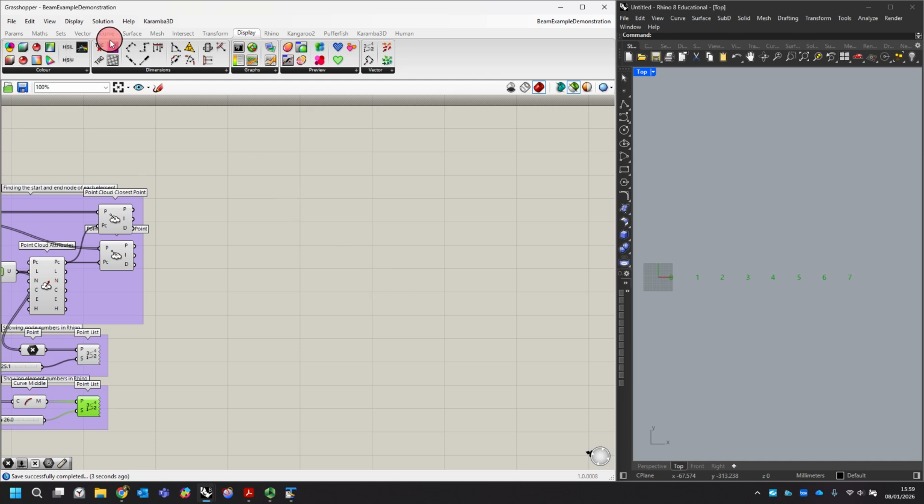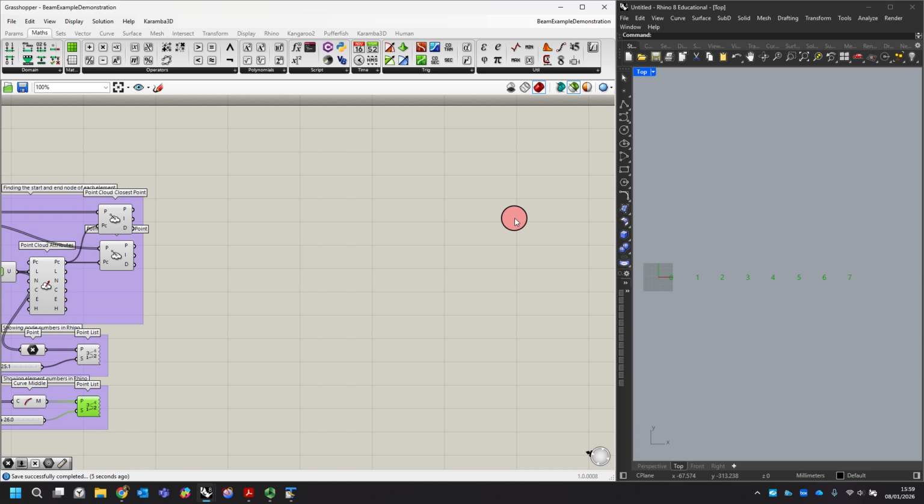And then we know that the Python component, so that's what we're going to use, is this one here that we're after, Python 3 script. And providing we've done everything correct previously, that will just go on fine. If it is going to try and load Python because it hasn't done previously, or any of the user packages, you'll see a little progress bar at the bottom of this component. So that'll let you know whether things are going well or not, basically.